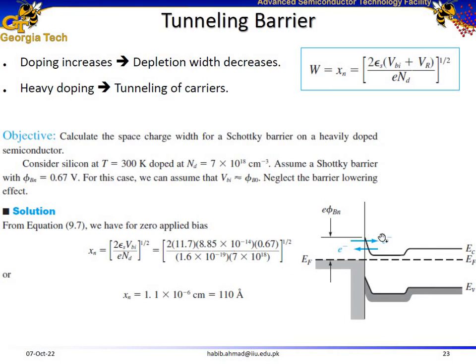Now look at the energy band diagram. What kind of materials do we have over here? The Fermi level is close to the conduction band, so it's an N-type material, but it's lightly doped. And then on top of that, we deposit an N plus material, where the Fermi level is super close to the conduction band. So this is our layer which is heavily doped, and this is going to result in tunneling. And then we have our metal on this side.